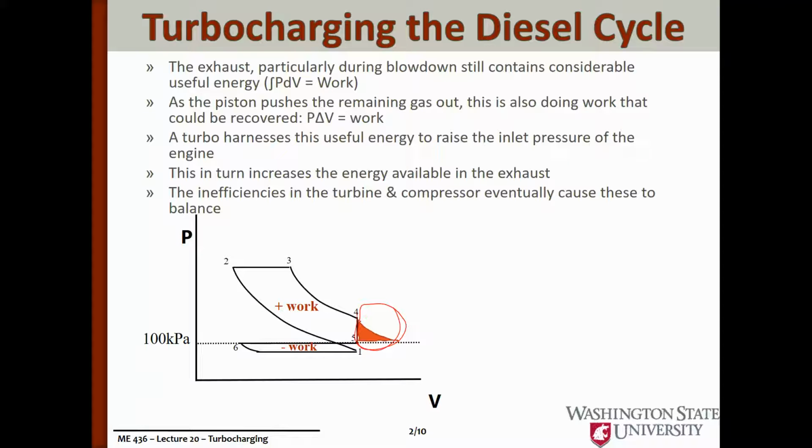There's still useful energy in that mass as it leaves the cylinder. And there's also useful work as the piston is pushing the final bit of the exhaust out. So the premise of a turbo is to harness a portion of that exhaust energy, convert it into useful work, and then use that useful work to turbocharge the incoming air.